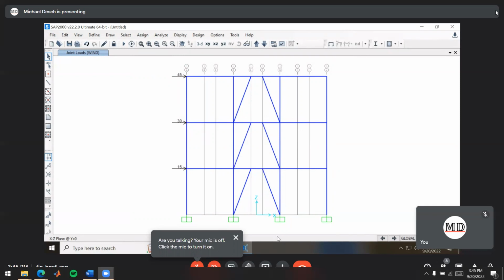But when you're actually practicing, it is more pinned than fixed a lot of the times when we're using braces like this. Actually, most connections are more pinned than fixed when they're detailed, and usually they'll call out connections on plans if they're supposed to be a moment connection. But moment connections take a lot more time to put together, so for today, we're just gonna keep it all rigid.